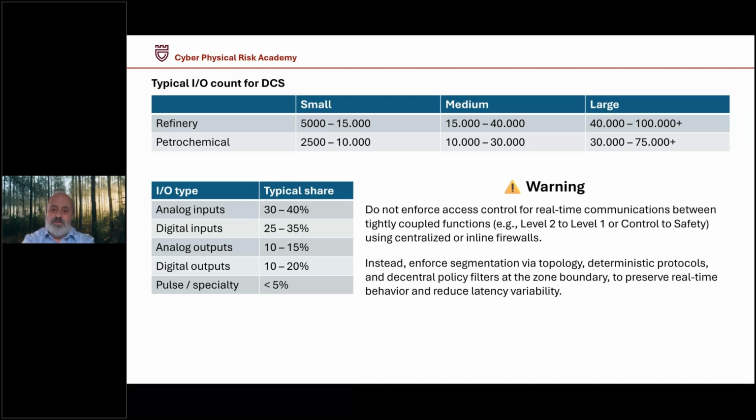You have to segment it such that your communication is guaranteed. So you cannot have all your controllers in a single segment because that would make life difficult. So you break up things, which is also following the natural flow of where you put your process controllers. In a very big plant, you have probably multiple equipment rooms in the plant. Now, petrochemical is smaller, but still big petrochemical complexes can be quite big.